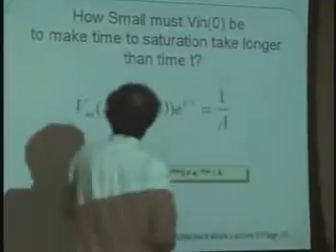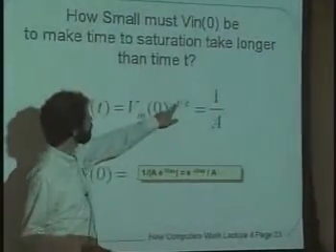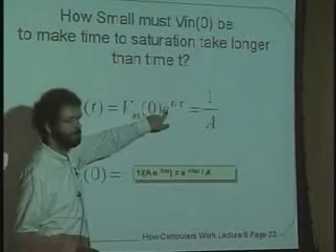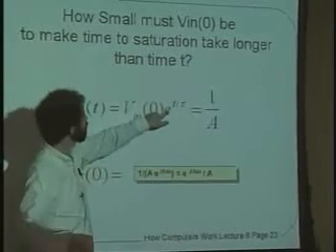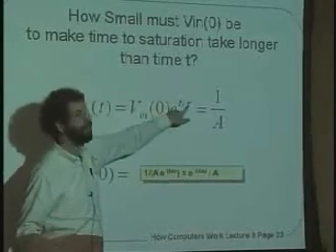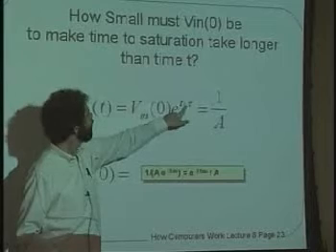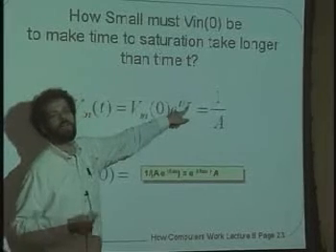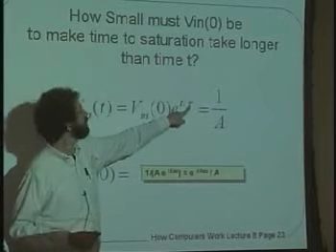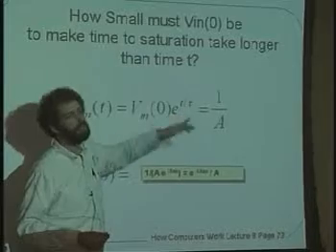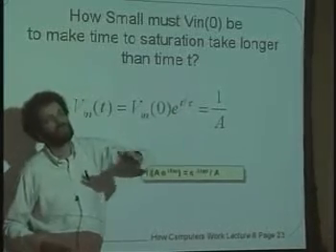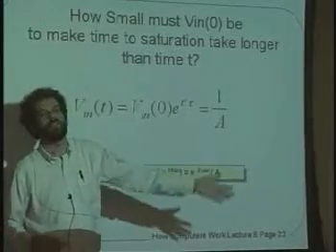So in fact, what we have is a function that looks like this. We have an exponent of the constant e, which is 2.71828, times t over tau. Now t is time, and tau is what's called the time constant of the circuit. If tau is big, it means that we take a relatively modest, slow way to get to one side or the other.